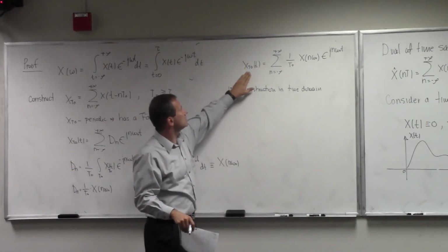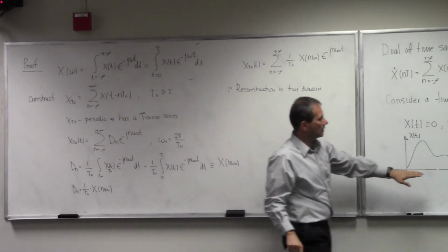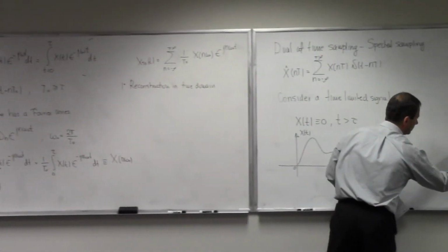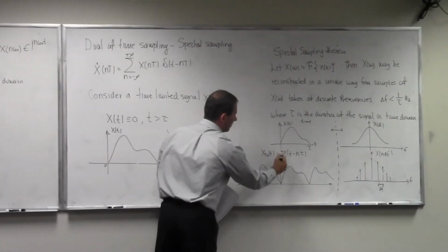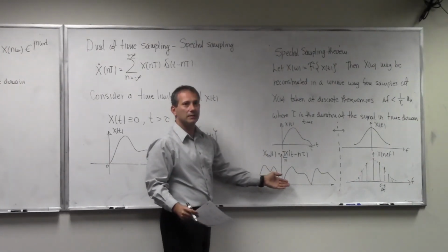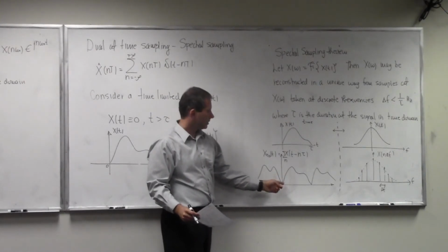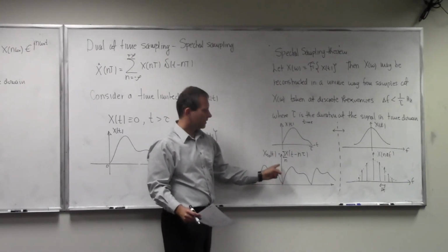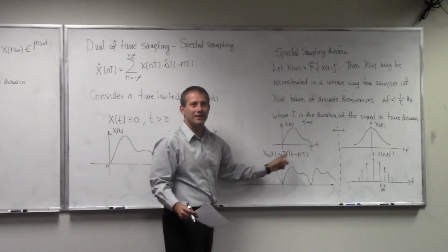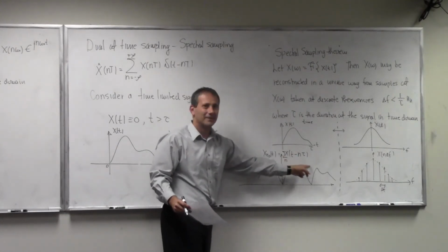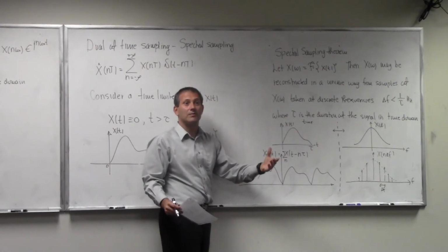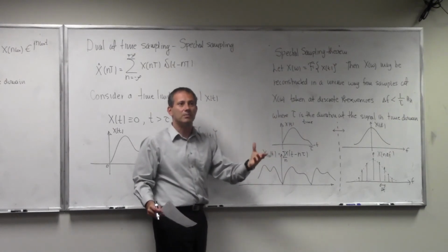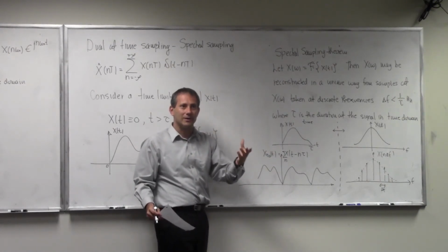So if I have the signal, this is my x T0 of t, right? How do I get my original signal? Not a sinc function. Low pass. I need to box this part, right? Low pass in the frequency domain meant multiplying with a rectangular pulse, right?